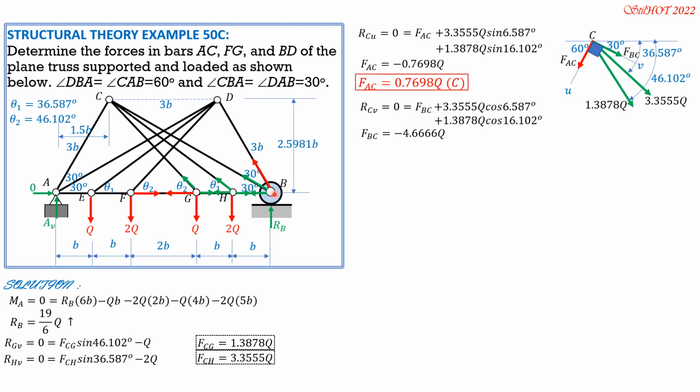These are the forces. And take note that this is F_BC, which is known. This is F_BD, which is unknown. So the equation is simply sum of forces vertical equals 0 at B. So F_BD sine of 60, the vertical component of F_BD, plus the vertical component of F_BC is F_BC sine of 30, then plus R_B.